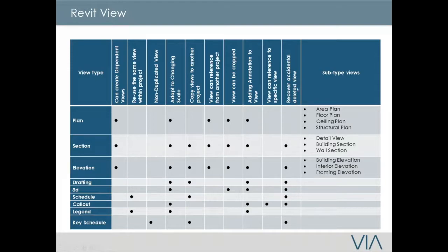Now the last one is going to be the most important, because people will delete stuff accidentally, and you have to find a way to recover it. The most critical is that sometimes when you delete floor plans, it's gone. You cannot recover it. So when users are doing a lot of this, you have to make sure you don't accidentally delete floor plans. The rest of the other views, when you delete them, you can still recover them.